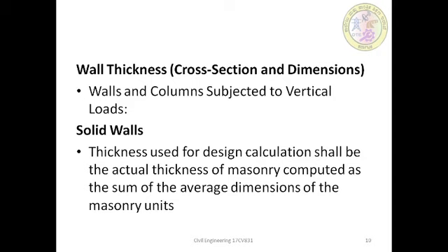However, in case of design of masonry based on permissible tensile stress, for example design of a freestanding wall, if the walls are plastered over, then the plaster of normal thickness is around 12 to 15 mm, with mortar of the same grade as used for the masonry, or M2 grade, whichever is the stronger. If the walls are flush pointed with mortar of M1 grade or stronger, then the raking thickness can be ignored.